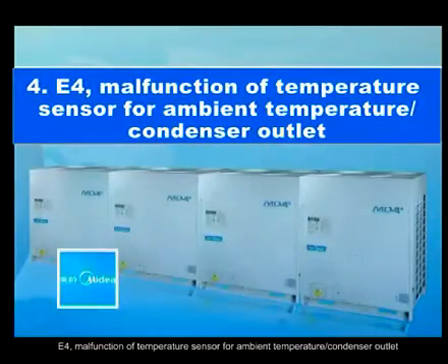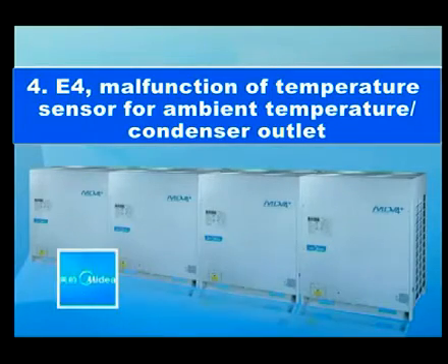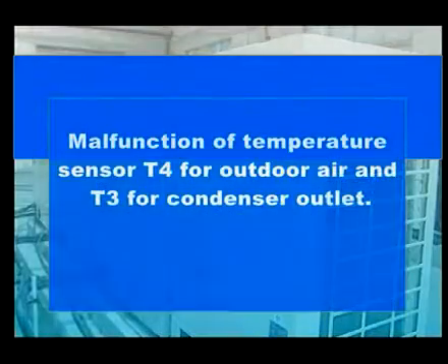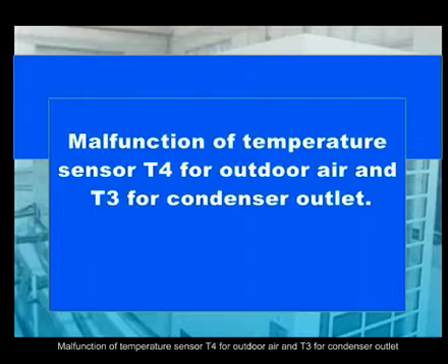E4. Malfunction of temperature sensor for ambient temperature/condenser outlet. Malfunction of temperature sensor T4 for outdoor air and T3 for condenser outlet.